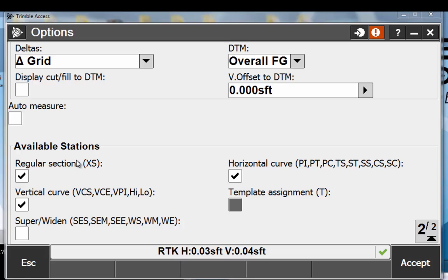Yeah, and a little nuance to know, we spent a few hours digging into this. If you have a corridor model that's 10-foot frequency, say, and you try to stake in between that, in a corridor model, you wouldn't necessarily want to cut a cross-section between two assembly insertions. So if you model that at 10-foot intervals and then you stake that to plus 25, so you're going to land in between.